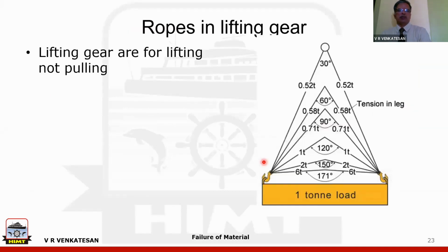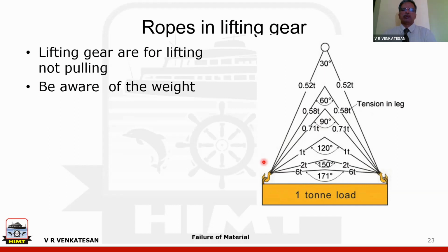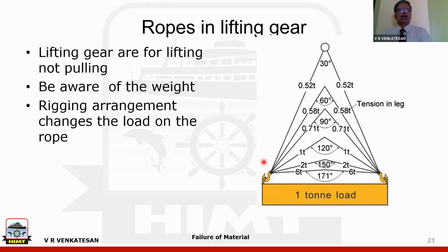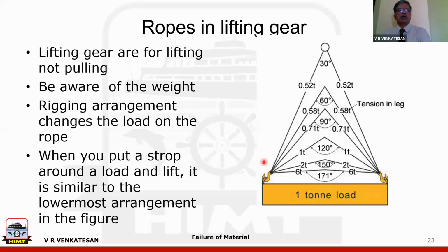Another very, very important principle is in lifting gear. Lifting gear is for lifting, and it is not meant to be used for pulling anything. That's an important principle you have to understand. And then, whatever weight you are lifting, you should know the weight. And then rigging arrangement will always change the load.